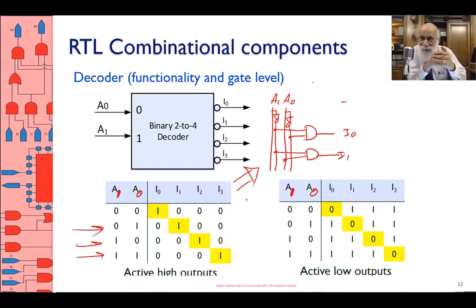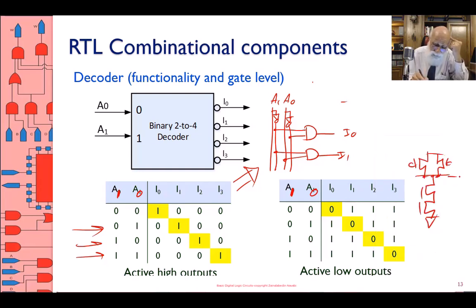And I find that the gates that I have been able to build using transistors, they all have NMOS transistors at the bottom and PMOS transistors on top. What it means is the gates that I have are either NAND or NOR. I don't have an AND. If I want to have an AND, I have to take a NAND and put an inverter on it.